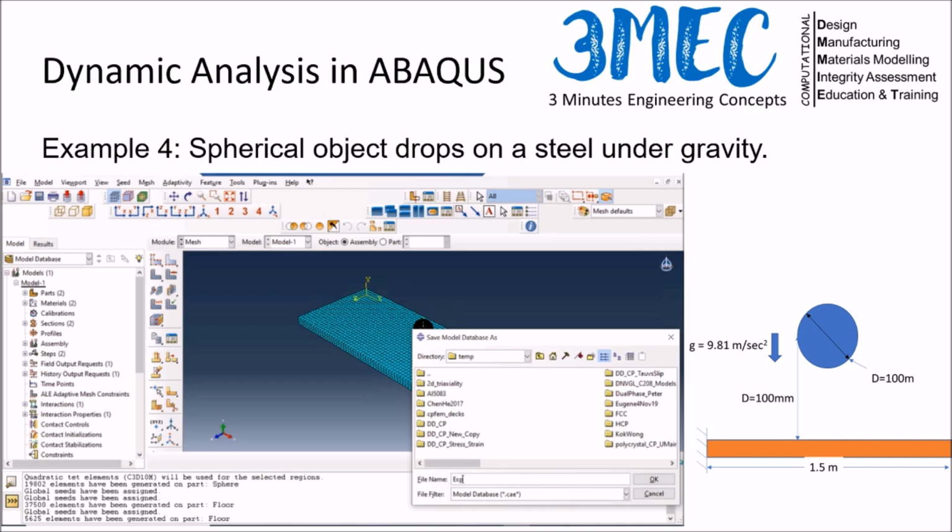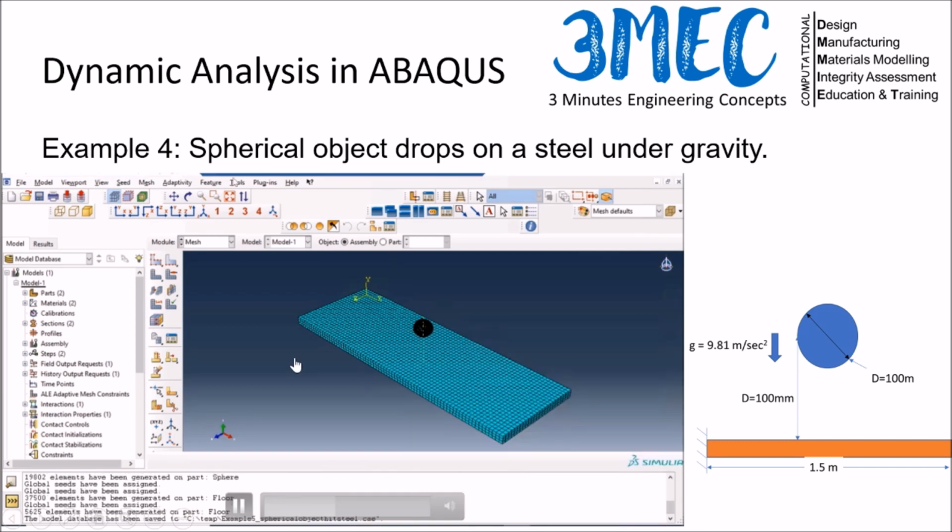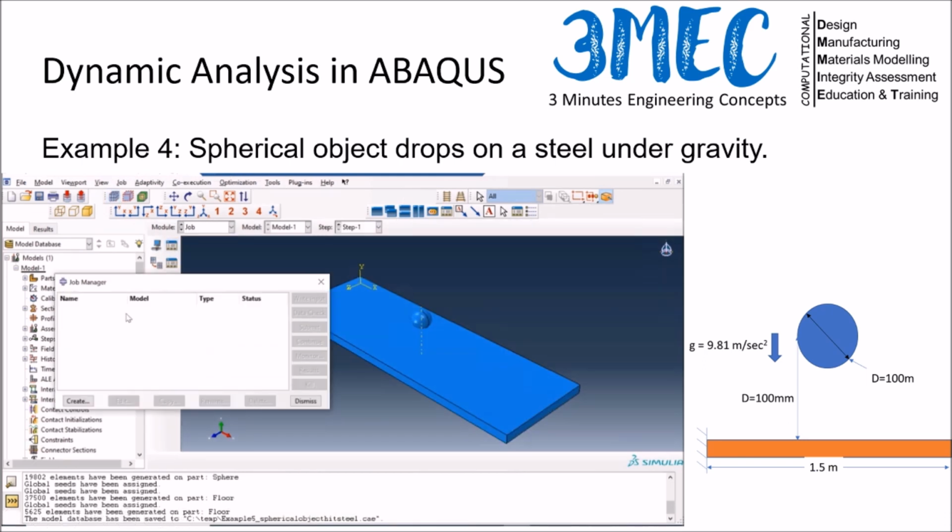because it's sometimes big jobs. When you start to submit, your CAE can crash and you don't know what's going to happen next. So it's better to save your job all the time. I normally don't prefer to use CAE to run the jobs, rather I use command prompt as I showed you in my other videos and lectures, because it uses a lot of resources as well.